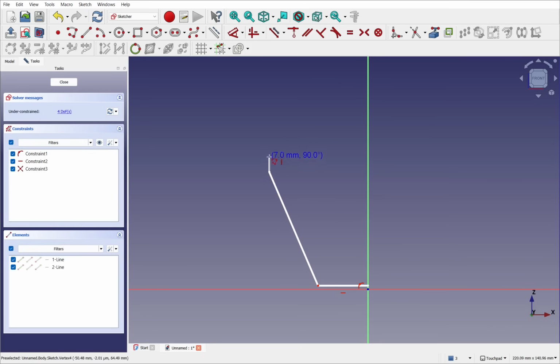Click, and then we'll come up straight. And don't worry if we come off, we'll add the constraint back in. And we want to go around about 40 millimeters. That's 39.2, but that's fine. And then just move the mouse pointer over to the left and right click to cancel the movement, and then right click again to cancel the tool.